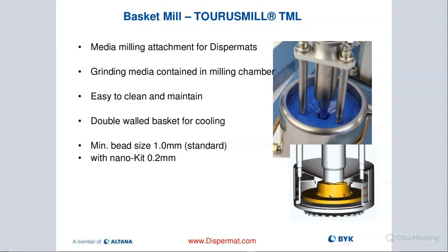So we purposely design a basket mill without a side screen and have only a screen on the bottom to improve cooling and reduce wear on the basket. And that's really important and effective. And we found out that the cowls blade on the bottom of our screen, right outside the basket mount, does a really good job moving the mill base out of the basket and then pushing it back to the top. So we do not need a screen on the side wall, and we don't want a screen on the side wall for the reasons I just mentioned.